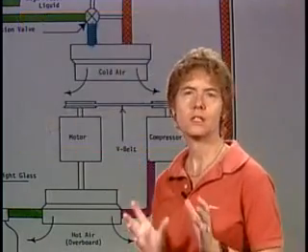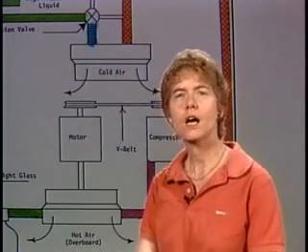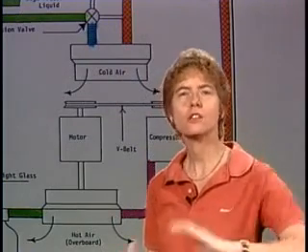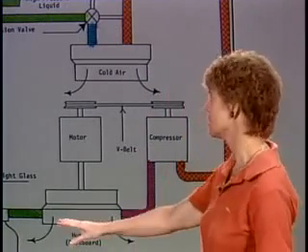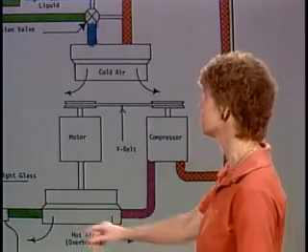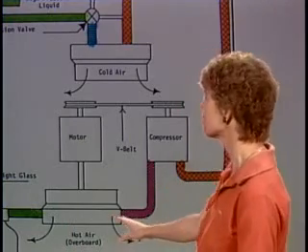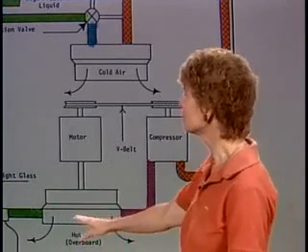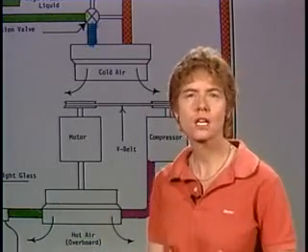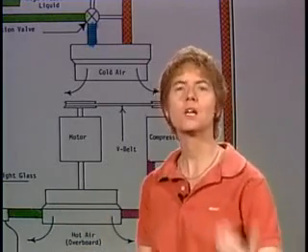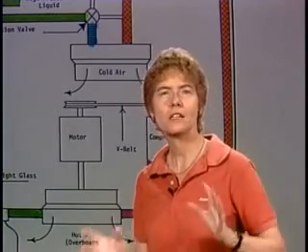Now, the point in the system where Freon gives up its heat and changes from a gas to a liquid is as it goes through this condenser, because it comes into the condenser as a high-pressure vapor, and it gets cooled off, and it goes out of that condenser as a high-pressure liquid. But it goes from a gas to a liquid, and it gives up its heat in the process.